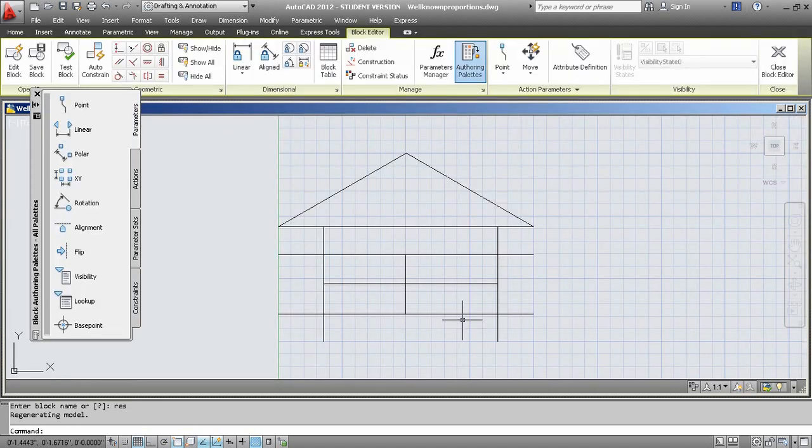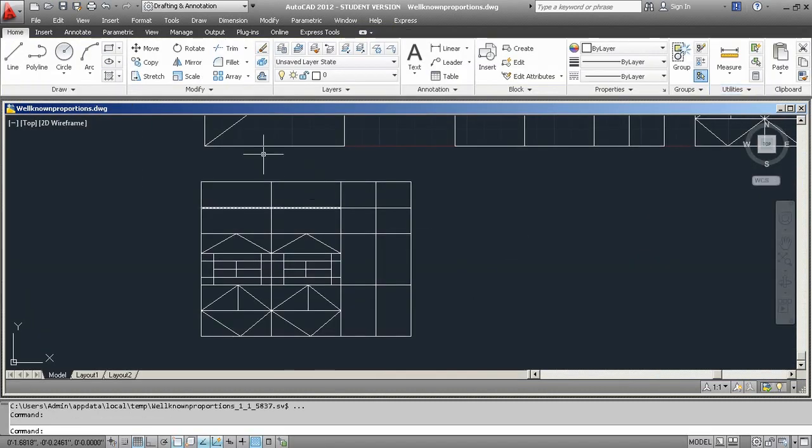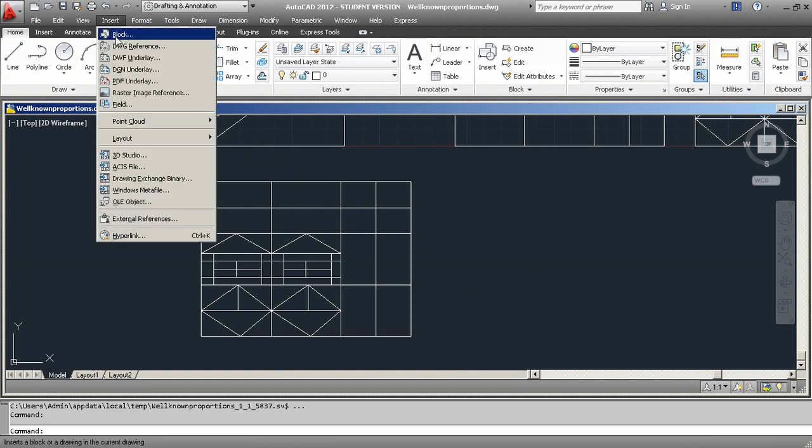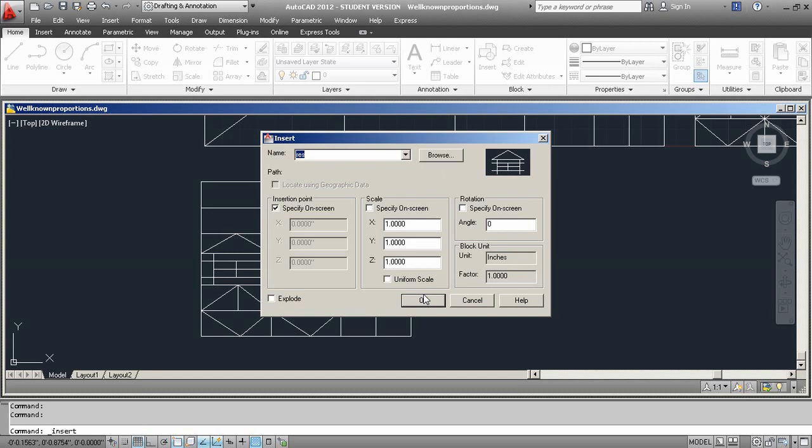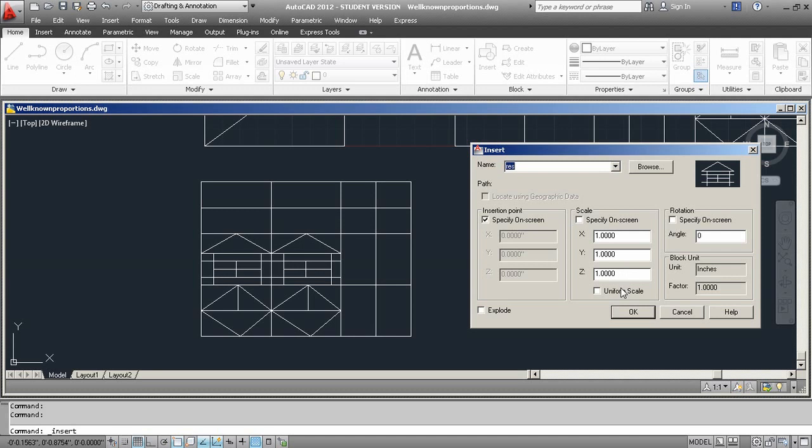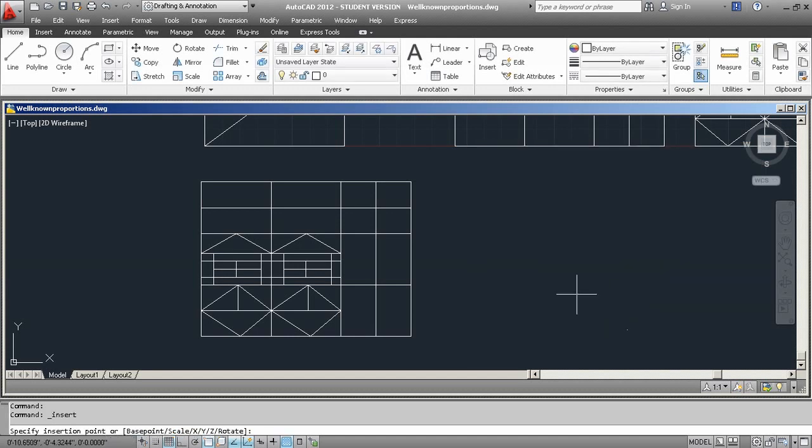When you do this, make sure that you close the toolbar. Now you can go to Draw and Insert. Insert the block, select the block, but make sure that you change the proportion in the X direction. That is crucial because the next area is half the size of where the block was created. So change the X direction to 0.5. Okay it, and see if we can insert this. It did. It worked just fine.